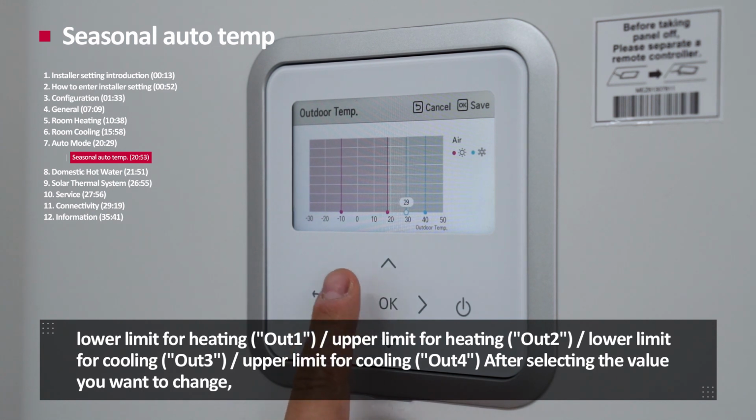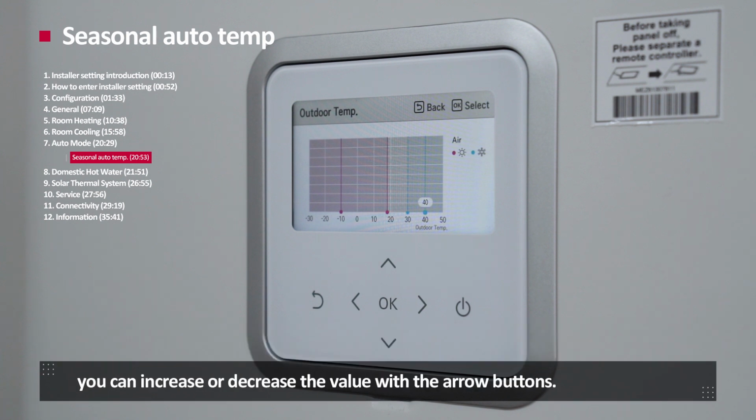Lower limit for heating, out 1. Upper limit for heating, out 2. Lower limit for cooling, out 3. Upper limit for cooling, out 4. After selecting the value you want to change, you can increase or decrease the value with the arrow buttons.